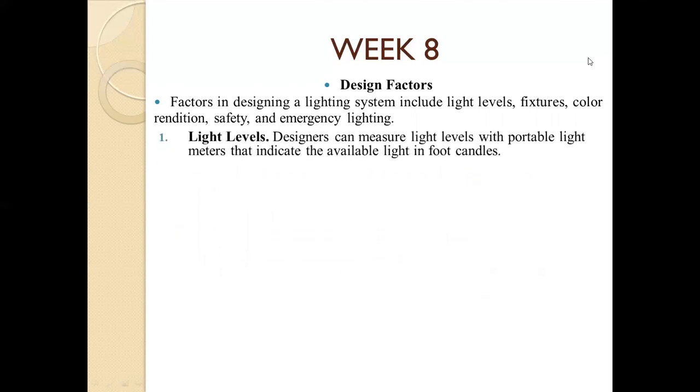For light levels, designers can measure light levels with portable light meters that indicate the available light in foot candles, and these devices are accurate to plus or minus 5% if kept calibrated. Designers may want to use more light than is recommended.